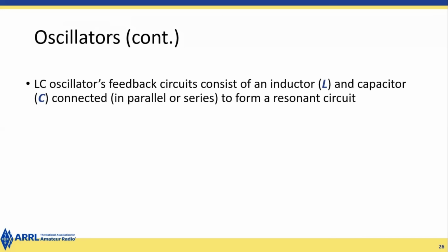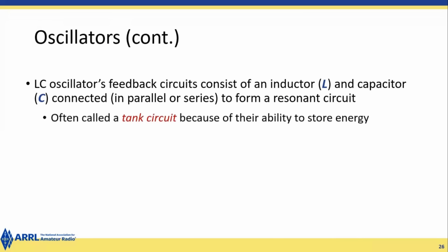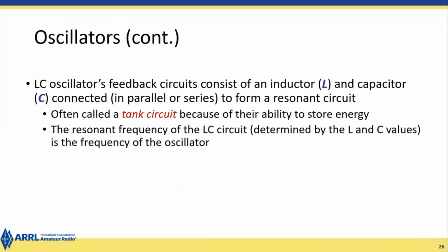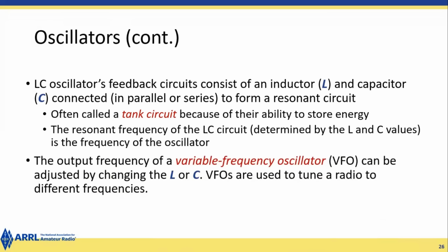An LC oscillator feedback circuit consists of an inductor and a capacitor, in parallel or series, that form a resonant circuit, often called a tank circuit because of its ability to store energy. The resonant frequency of an LC circuit, determined by its values, is the frequency of the oscillator. The output frequency of a variable frequency oscillator, VFO, can be adjusted by changing the L or C. VFOs are used to tune a radio to different frequencies.